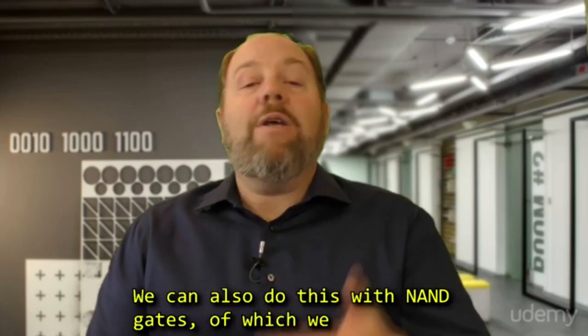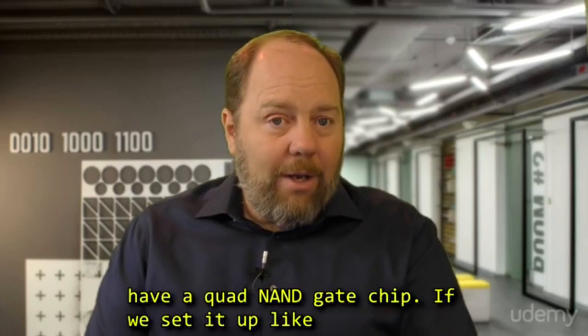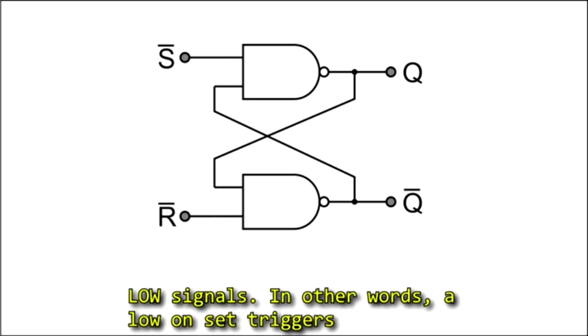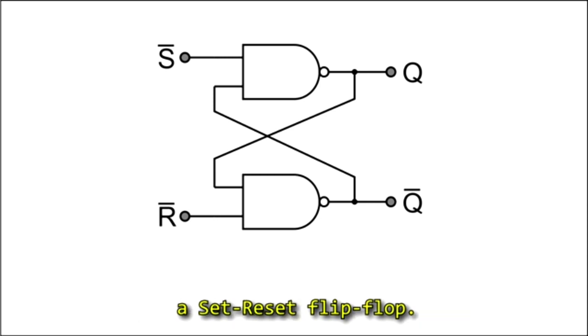We can also do this with NAND gates, of which we have a quad NAND gate chip in your kit. If we set it up like this, it does the same thing as our previous flip-flop. However, it is set and reset with active low signals. So in other words, a low on the set input triggers Q to go high. Now this is certainly still useful. This is called an SR flip-flop or a set-reset flip-flop.